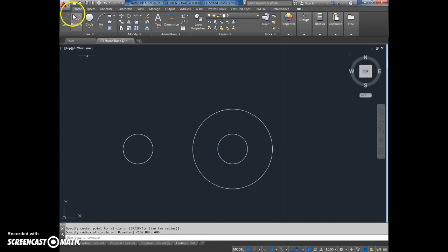Enter. And then what I'll do is I'll draw a line. I'll draw my line coming back along the x-axis by 160. And I'll just run a straight line up along here. And now I know where these 2 points intersect is the center point of my next circle. Okay? So where these 2 points intersect, because it was 400 at an angle this way, but it was also 1600 out this way. So it's where these 2 points cross.